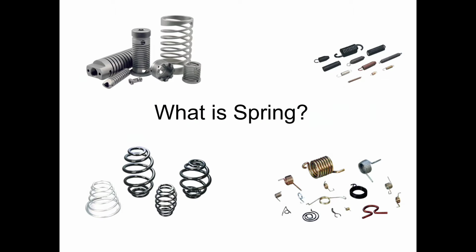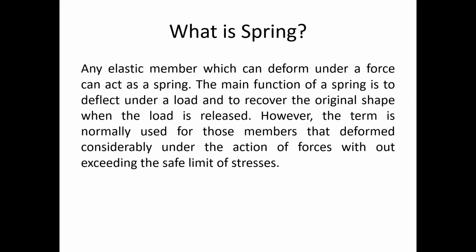So what is spring? By definition, any elastic member which can deform under a force can act as a spring. The main function of a spring is to deflect under a load and to recover the original shape when the load is released. Now you may ask, does that mean each and every elastic member can act as a spring? The answer is no, because the term is normally used for those members that deform considerably under the action of force without exceeding the safe limit of stresses.